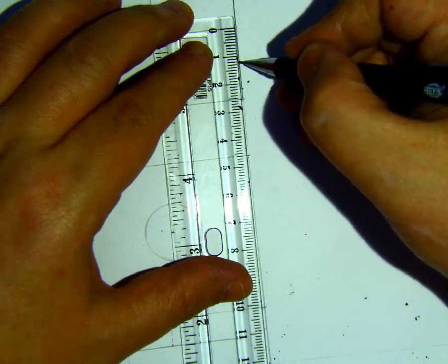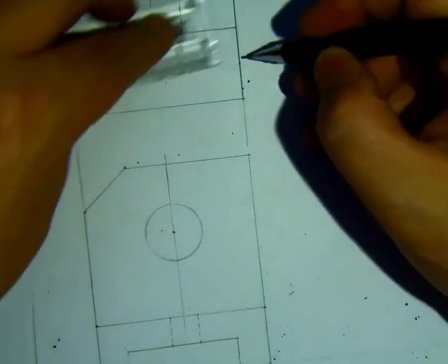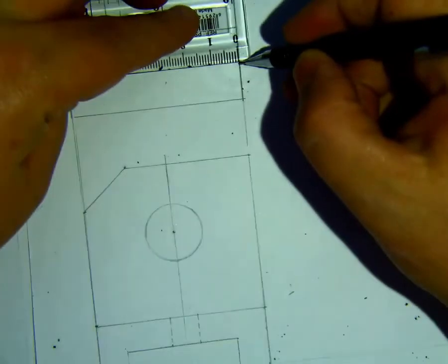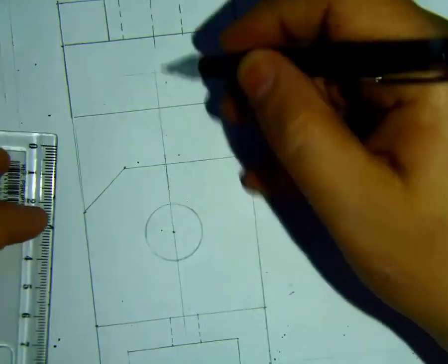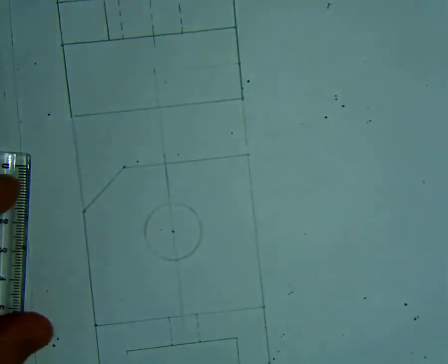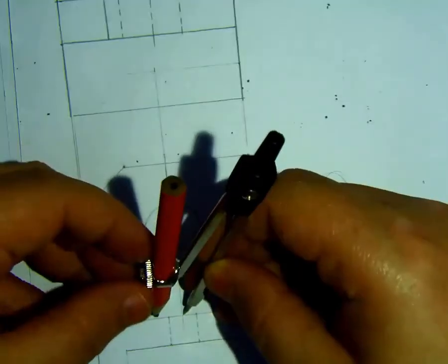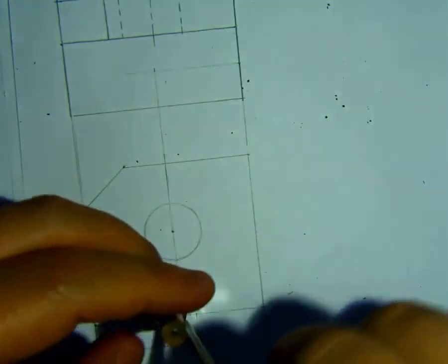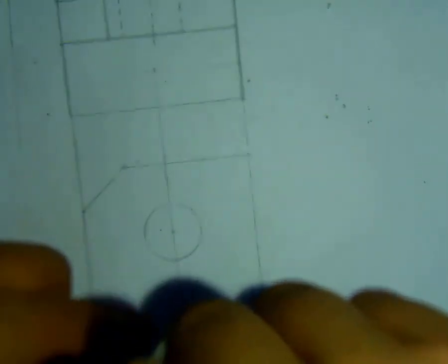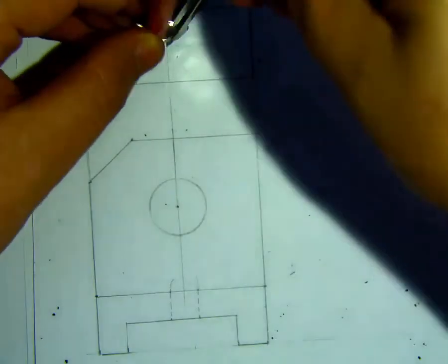This is 10, 11, 12 and a half. Yeah, somewhere here. Okay, I will draw thin construction lines, trying to keep them horizontal, and then I will connect it with this one here because they are in the same center. Then I will draw my circle. As we know, this is the radius because it will be from here to here. I will not draw the total on this view, I'm just taking the measurement. I'll draw it in the top, of course.